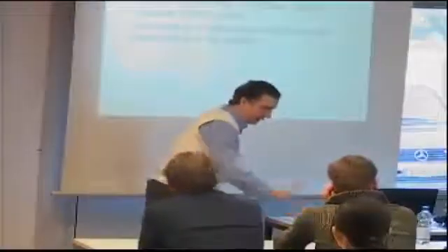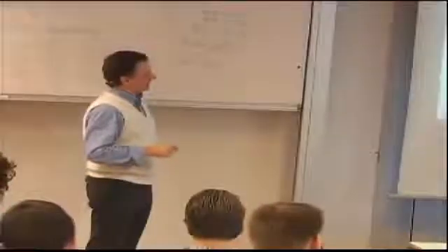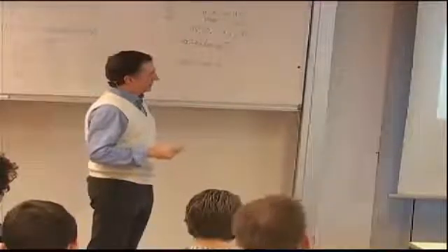So for now, let's say it's long enough, and that means I will only use the 2 phi values, and I'm adding the constant K0 again from the theory of the Fourier series, because I need it for reasons that will become obvious in a second. Having determined sigma x, I can then use my equilibrium equations to determine sigma y and tau xy, which is just straight differentiations and integrations from this expression here.